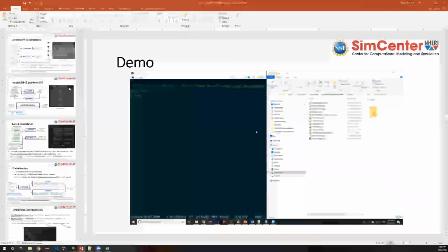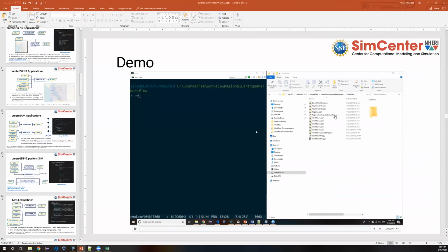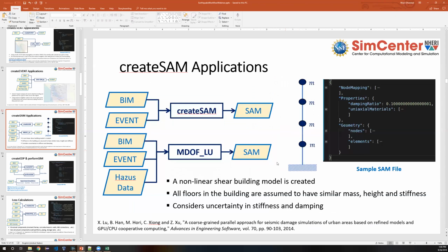Okay, there is another question that maybe we can talk about. Someone asked, how does this simulation take into account the building element model nonlinearity, the damage residual quantification? Is it from current or available OpenSees elements? Yeah, that is the case. If you look at this reference, it actually goes through the process of creating these nonlinear shear building models. Basically, it uses zero-length elements in OpenSees for the nonlinearity. It's a model that includes also degradation, so nonlinearity and degradation in the structure strength.